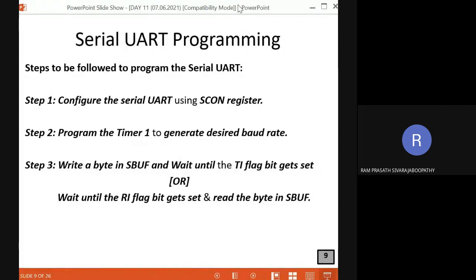It means that if at least 1 byte of data is available, it will start executing the next line. Some data is there. We have to read it and print it, so Serial.read. These are the things you have done in the Arduino IDE. Now we are going to do the same thing with the microcontroller.